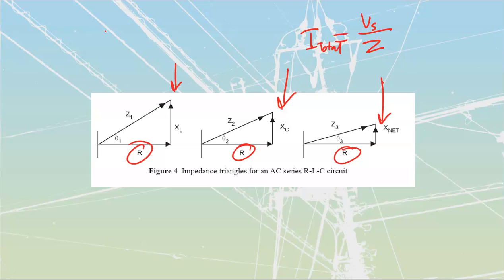This can cause a lot of danger, where people think that they've got a 120 volt circuit, but in reality, they're going to have some components that could be up at 500-600 volts. It can also cause danger of explosion or fire, because if you've got components like capacitors that have a working voltage, and you place them inside there and take that circuit to series resonance, all of a sudden the voltage you're actually placing across that capacitor could be way higher than what it's rated for.